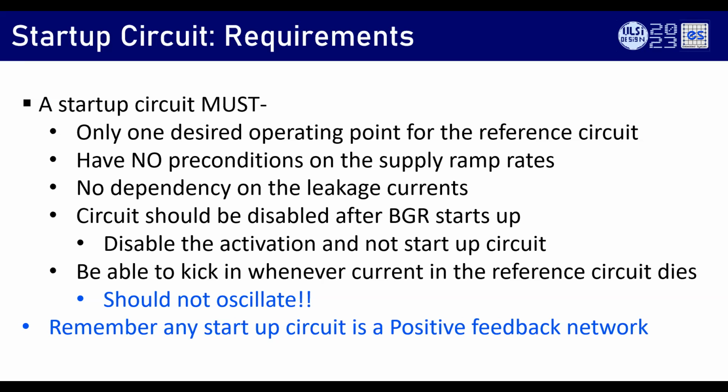Okay. And the requirements of the startup should be that after designing the startup, there should be only one desired operating point for the reference circuit. You can't have multiple. And you can't have any conditions on the supply ramps. Your supply can come up with whatever ramp rate it needs, but your bandgap should come up. And there should not be any dependency on the leakage current. And the startup circuit should be disabled after the BGR starts up. Okay, once the bandgap reference starts up, your startup circuit should be disabled.